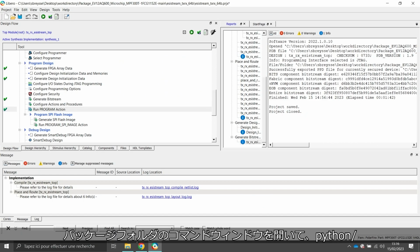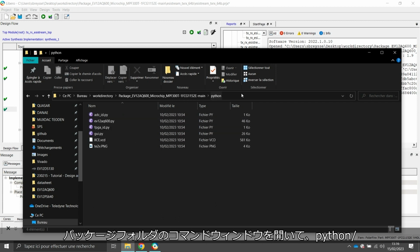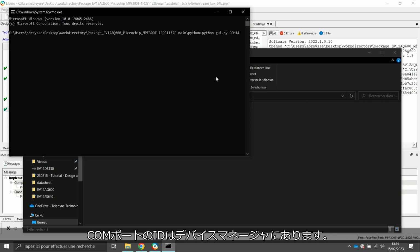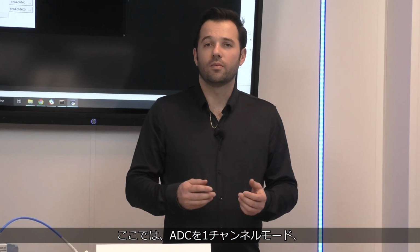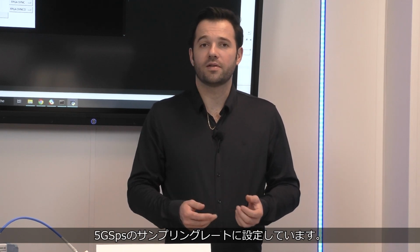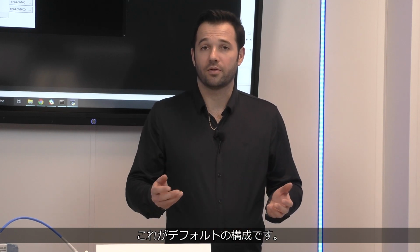To do so, open a command window in the package Python folder and type python GUI.py COM plus the ID of the COM port. You can find the ID of the COM port in the Device Manager. For this demo, I configure the ADC in one-channel mode and a sampling frequency of 5 gigasamples per second. This is the default configuration.